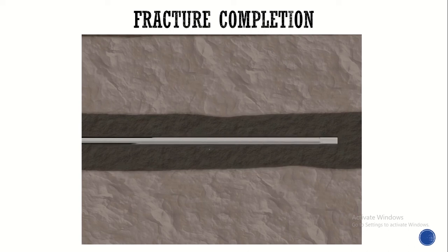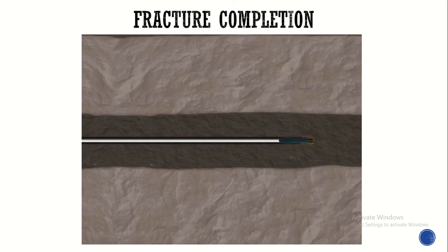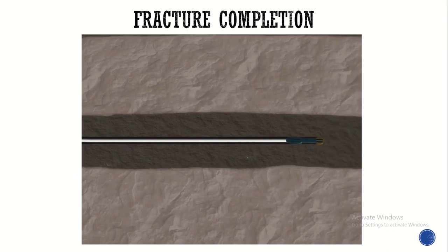A natural fracture, or one that has been hydraulically fractured. The fracture is treated as a slab of high permeability that is an effective extension of the actual wellbore. Flow is from the reservoir to the fracture and through the fracture to the well.